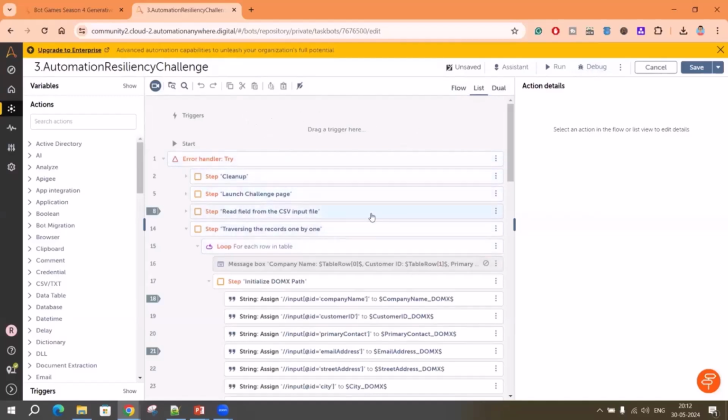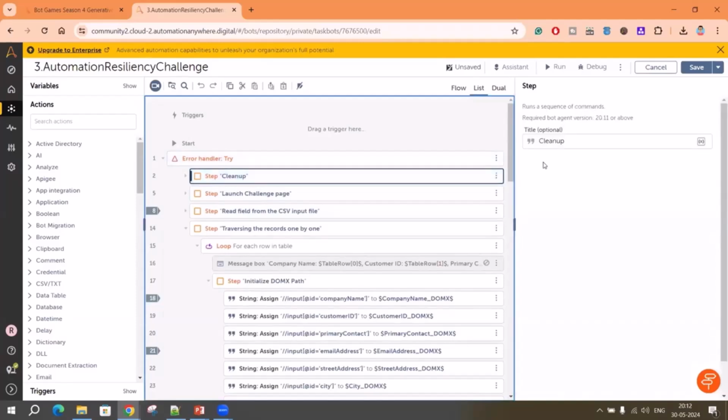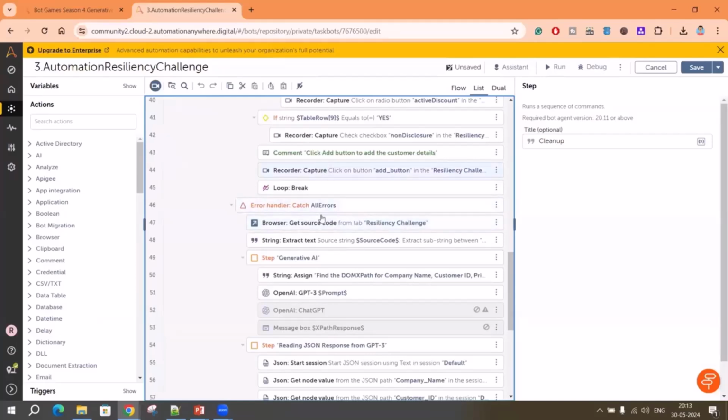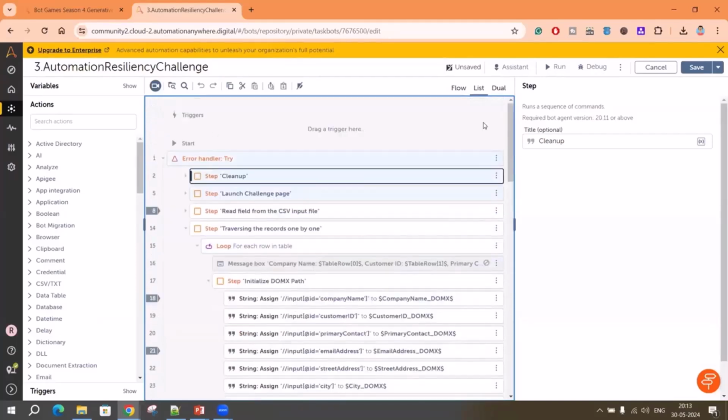bot that there are no validation errors. What I mean by validation error: for example, if you are using a command to read a file and you have not provided a file, that is a validation error. The command is incomplete. In that case, you will not be able to run this debug and you will not be able to use debug options. So you have to make sure there are no validation errors. All the commands that you are using here are complete.